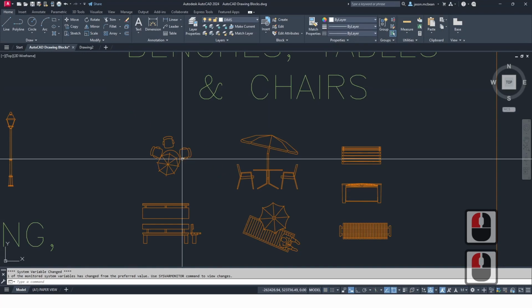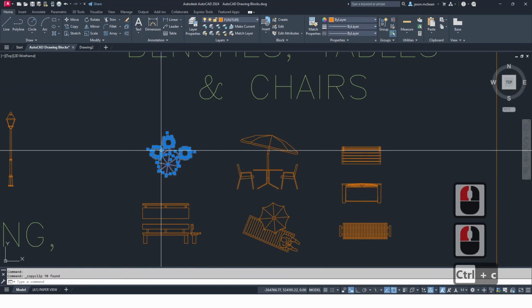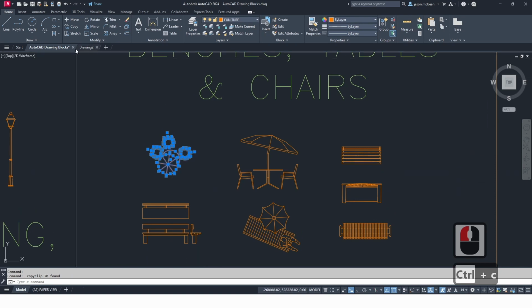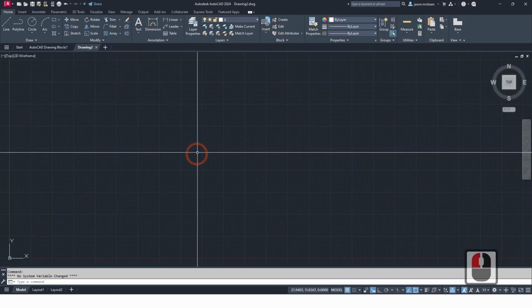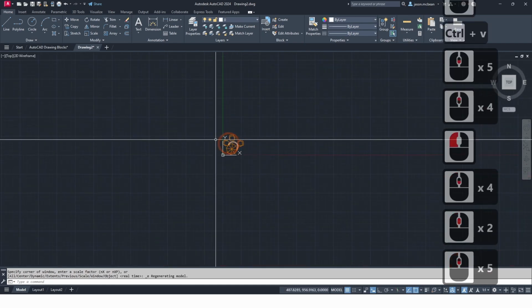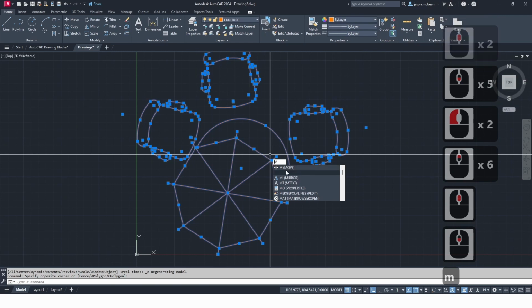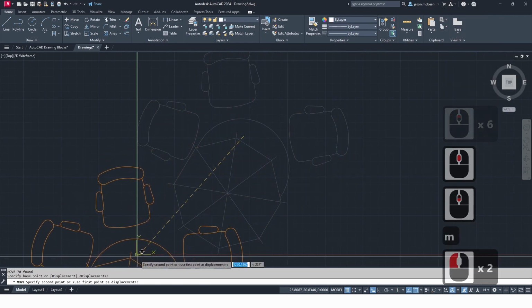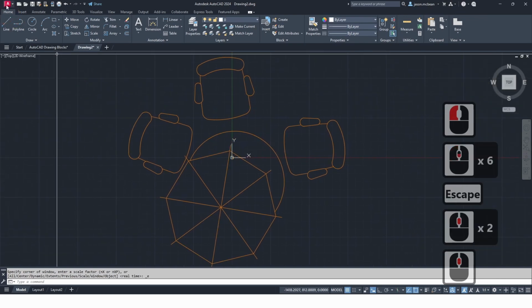Then you're going to go to the AutoCAD file, select the information, Control C, just like I've done here, and I'm going to remember the layer. It'll keep the layer. Control V, and here I'm just going to paste it anywhere and zoom in. Now you want to move this information as close to the center as possible. Okay, great. Now I can save this drawing.